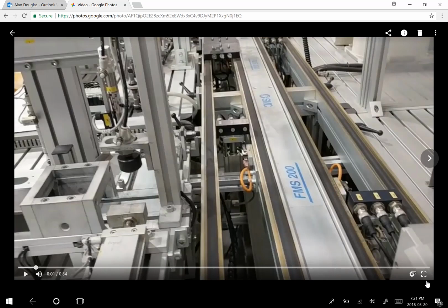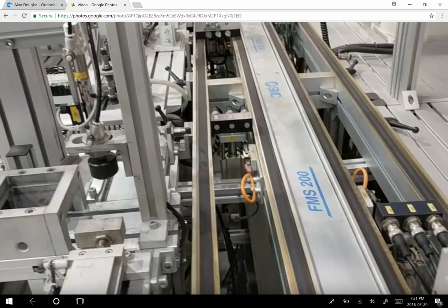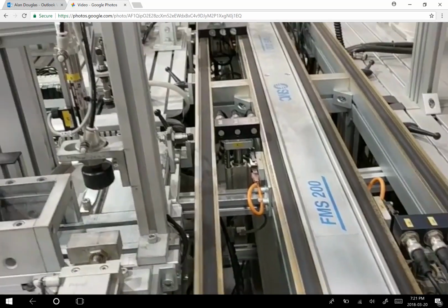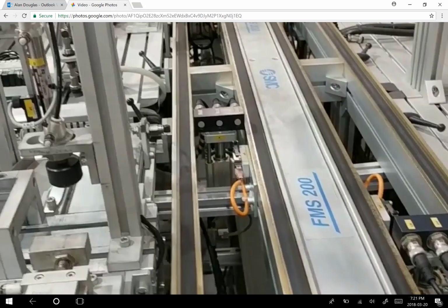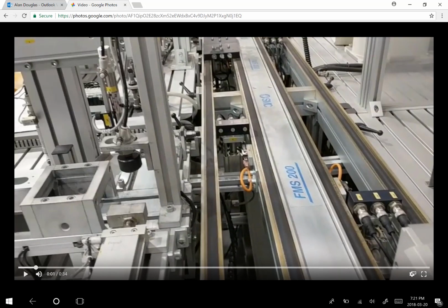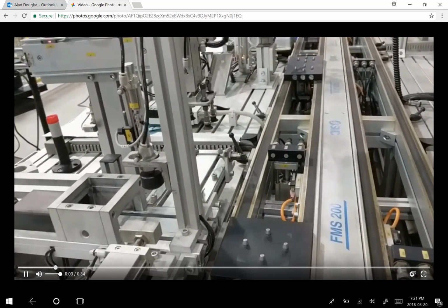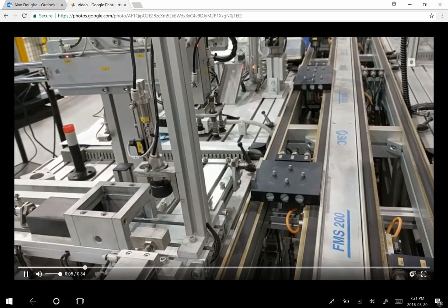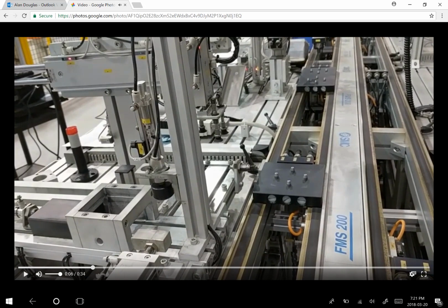Okay, so let's look at the way this station is going to run. This is station number 1 on the line right now, so you can see the pallet stop in the middle there. That is this guy here. That is the pallet stop. What's going to happen here, you're going to see the pallet when I play here. The pallet is going to come into the stop. At that point, we have read pallet present.